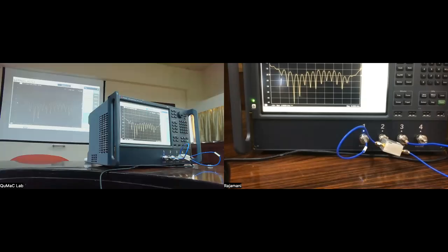So if this is amplitude V, remember it's half power, so the voltage here will be V over root 2. This will be V over root 2. And this again, because it's sum, it's going to be V back here. So if the two splitters are identical, then this would happen. So this is one way of putting signals in with the precise phase relationship between the two, but there are other ways of doing that.